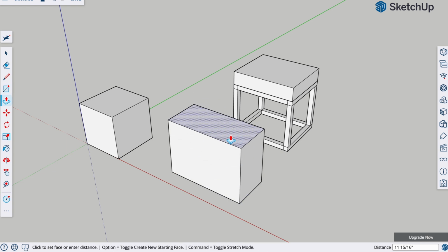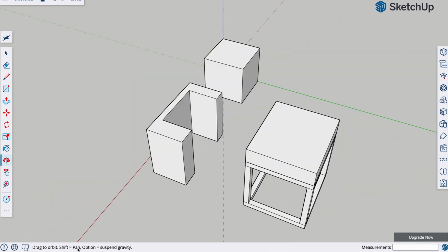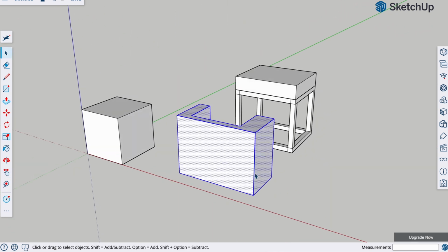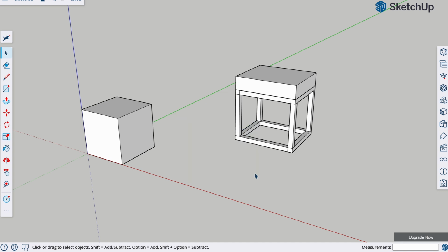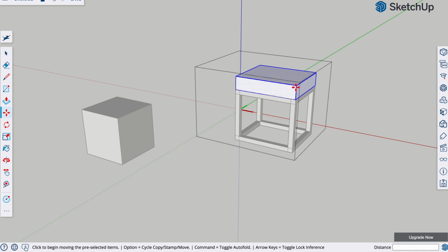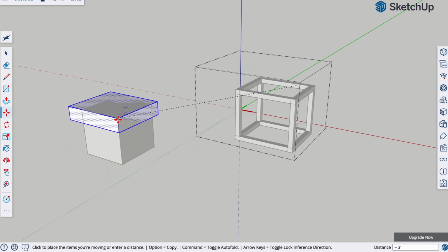Okay. So to recap, before we get into building the actual camper van layout, R is a rectangle. P is a push and pull. Oh, I guess I didn't show the pull. So the pull is, within this module, you could do this and draw another rectangle. P, and instead of pushing, you could pull to make it hollow. So there you go. That's what it would look like if you pulled, which is a great way to create hollow objects. So that's R, that's P. M is move. So hit that corner, move something around.